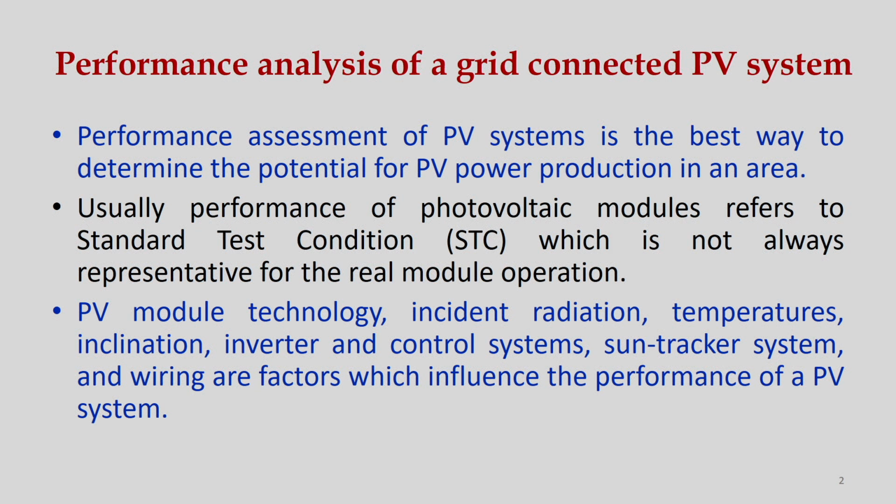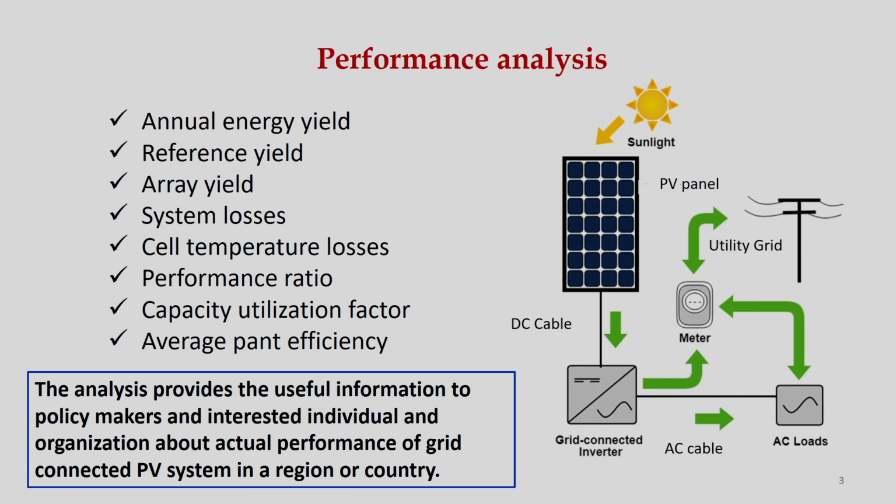So, when we call performance analysis, what are the parameters it includes? Annual energy yield, reference yield, array yield, system losses, cell temperature losses, performance ratio, capacity utilization factor, average plant efficiency. These parameters we must know.